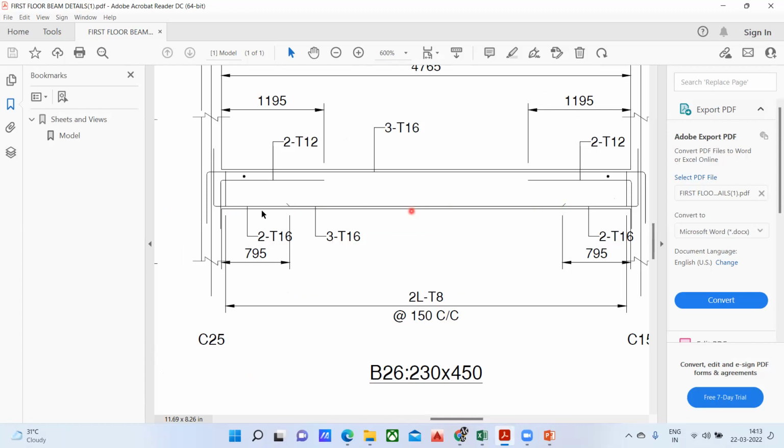But the only thing is, it will be curtailment. You won't get all those things in the Excel sheet. Practically, this is what we follow. Instead of providing this bar completely, in this way we'll try to curtail, and this is what we do as the curtailment. Up to here only, my maximum bending moment, that is the sagging bending moment, is up to this distance. That is why I'll provide additional steel in this direction. Got it? You can do the curtailment there.